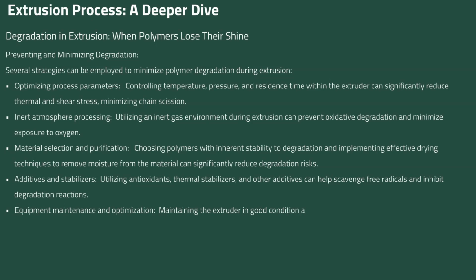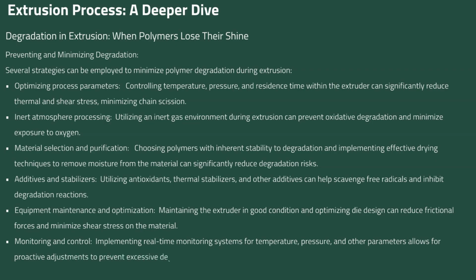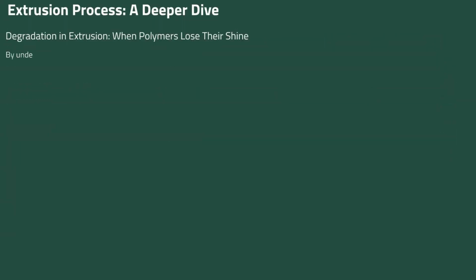Equipment maintenance and optimization. Maintaining the extruder in good condition and optimizing die design can reduce frictional forces and minimize shear stress on the material. Monitoring and control. Implementing real-time monitoring systems for temperature, pressure, and other parameters allows for proactive adjustments to prevent excessive